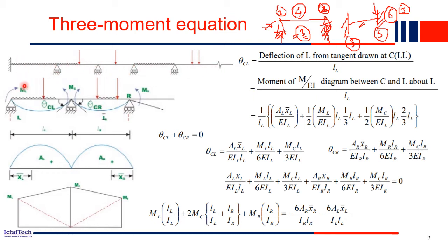This is a very real-life problem. If you look, all the beams are actually continuous beams, not a single beam. Unlike this one, our real structures are continuous beams, and the structures are highly indeterminate in nature. But till now we discussed how to solve determinate beams, that is, simple structures. So today we'll employ the three-moment equation to solve continuous beams. So how to do that? Why is the equation called the three-moment equation?